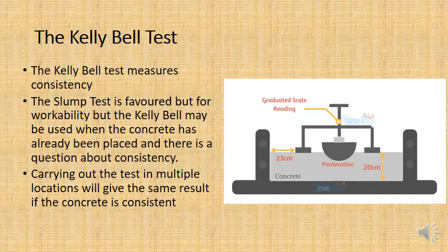And that's common practice, and most contractors and construction people know that. You test the concrete to make sure it's workable enough, and then you place it. If it wasn't workable enough, then you're going to have trouble compacting it.